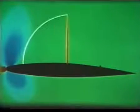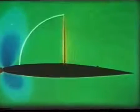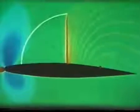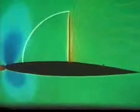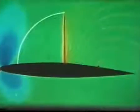On the rear part of the wing, every point, such as this one, sends out innumerable tiny pressure waves at the speed of sound. In the forward direction, these waves meet airflow in the opposite direction and make less and less progress until they reach a stage where they can't travel any further forward because the airflow itself is moving backwards supersonically. It's like trying to step off an escalator going the wrong way. The pressure waves constantly pile up here, and this is the shock wave.